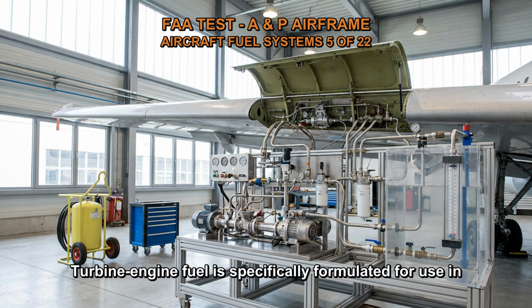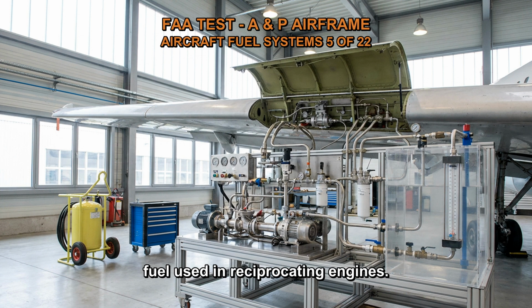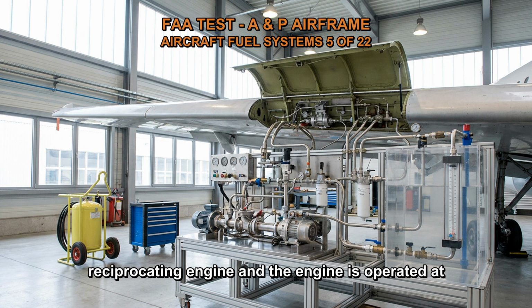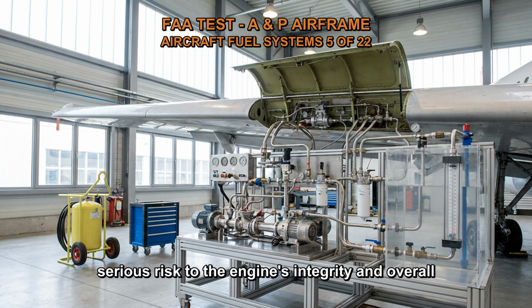Turbine engine fuel is specifically formulated for use in turbine engines and has different properties compared to fuel used in reciprocating engines. When turbine fuel is mistakenly used in a reciprocating engine and the engine is operated at takeoff power, severe detonation can occur, posing a serious risk to the engine's integrity and overall safety.